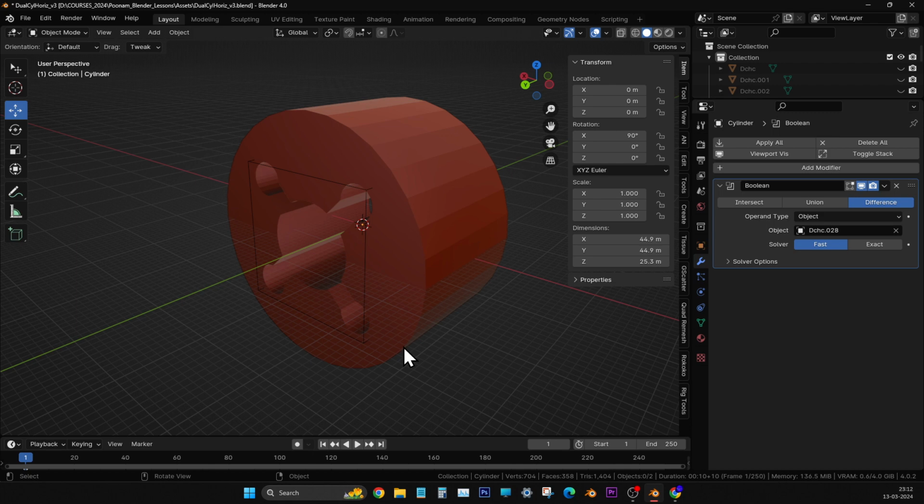No, sorry, you have to go to File, Import, and then the dot STL option down there. Yeah, that's the one. So when you imported it, it came in separate, I think. That is why it is coming this way. For me, it came as one single object.